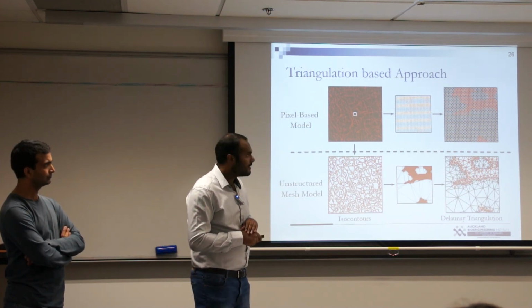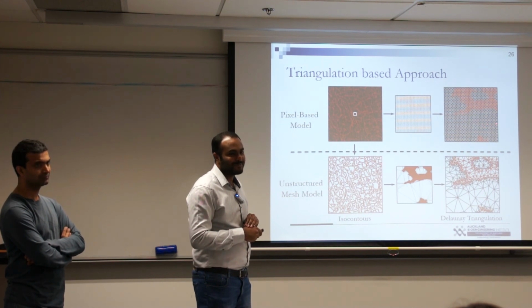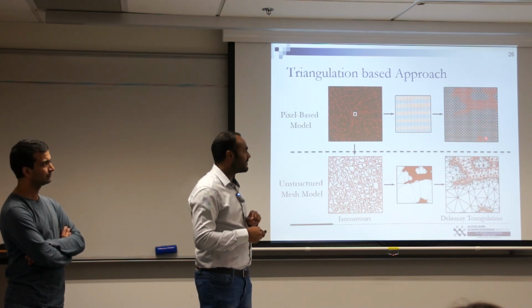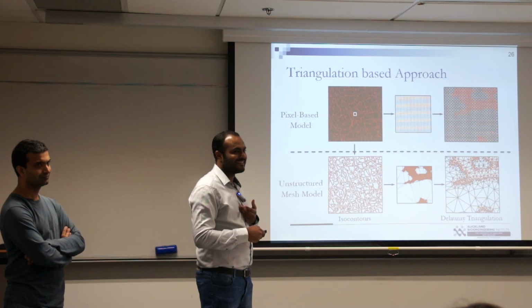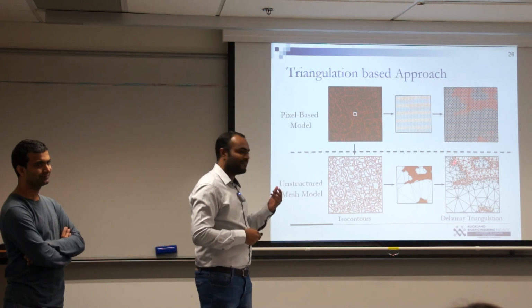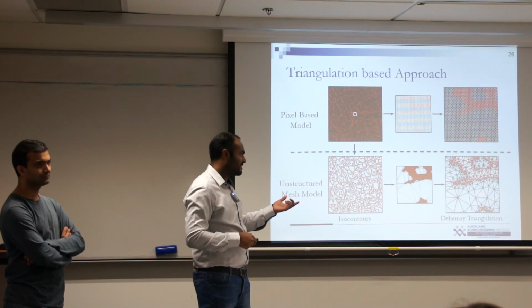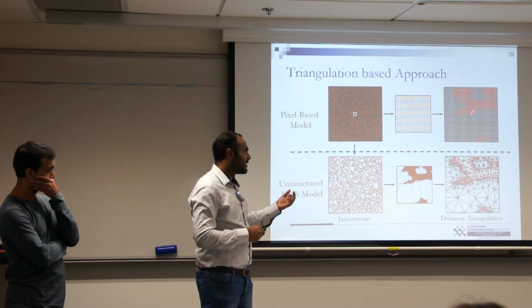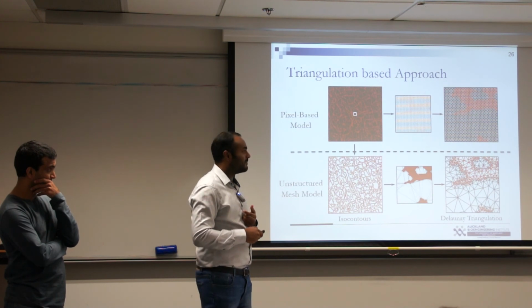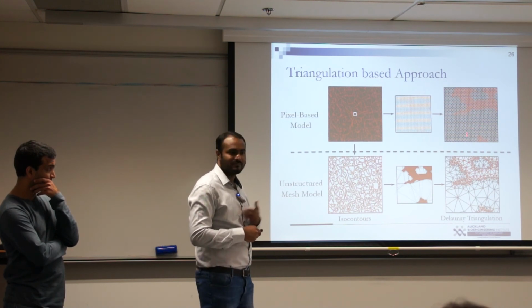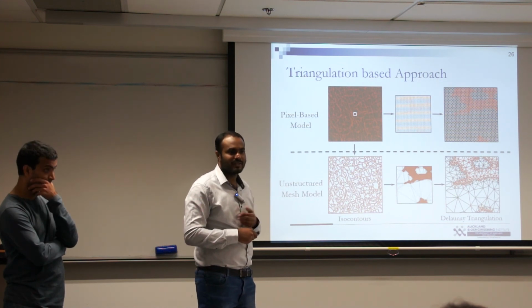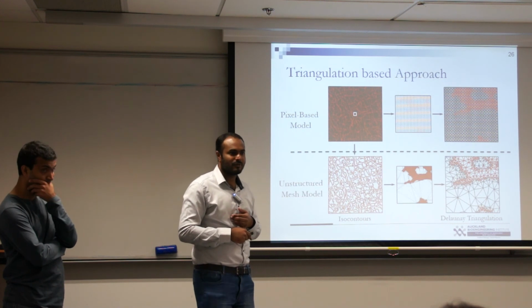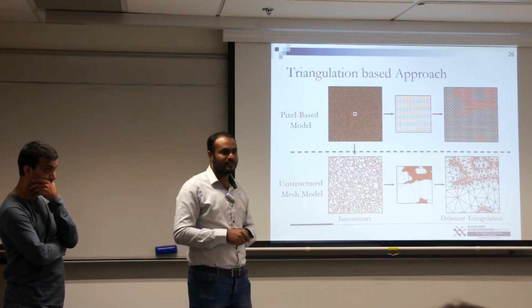Did you refine the top one as well? Well, it's already very, very small. You would suggest that probably this is not converged. We tried to reduce the size of the unstructured mesh to a very small size, but again there was a considerable difference. We didn't reduce the size of this one, as we assumed that it might be converged. So probably that should be the next step we do. Yeah, thanks for the session.